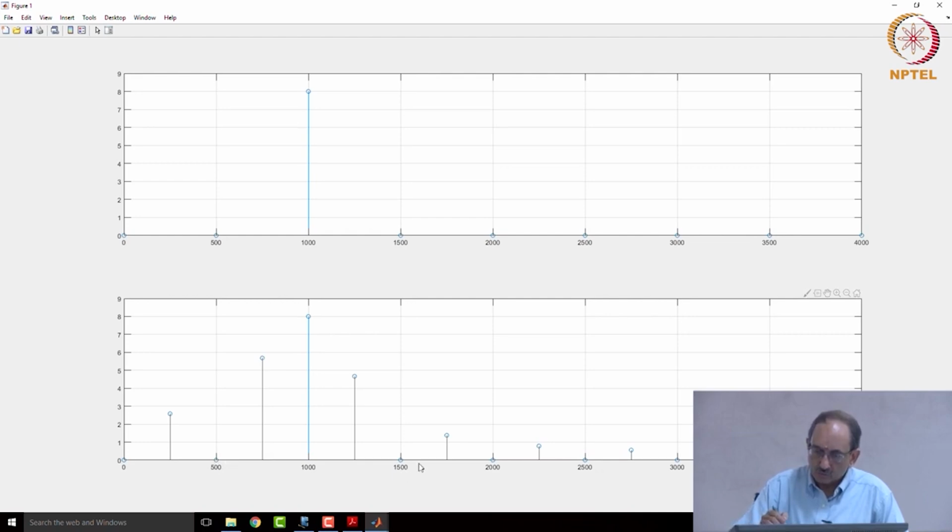So, wherever the original frequency points are there, you have those samples as before, but in between you have new samples. So, between 500 and 1000 there was none before, whereas you have this. Similarly, between every old sample you have a new sample value from the 32 point DFT.